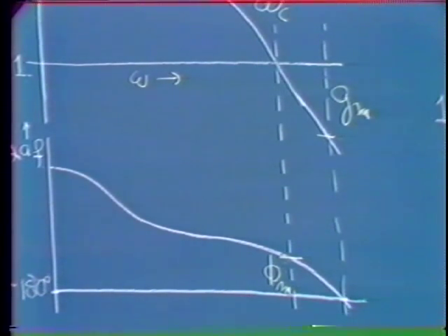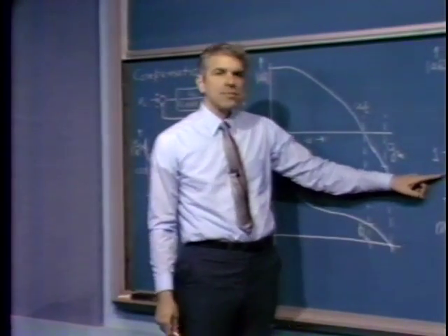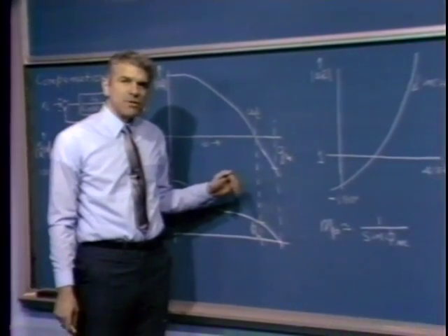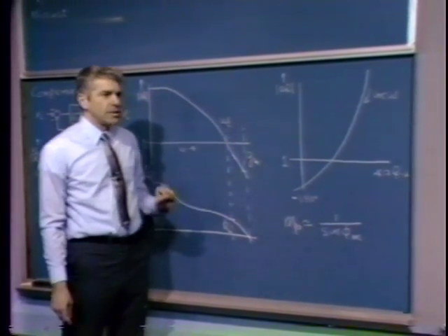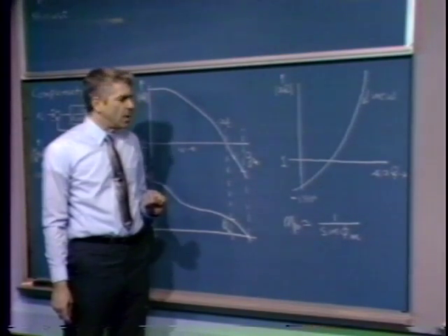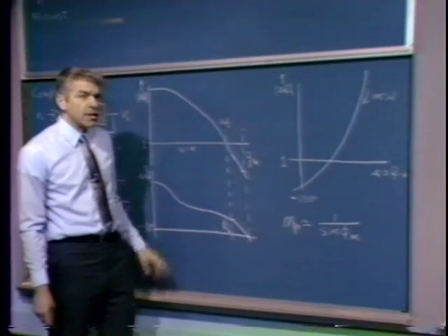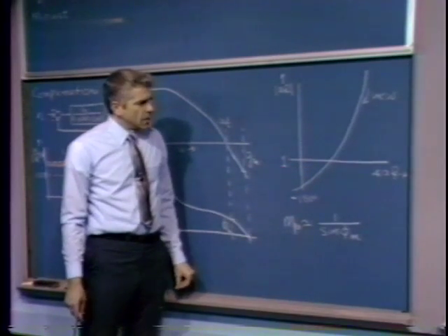We can look at those same quantities in a gain phase plot if we care to. We frequently do use gain phase plots for Nichols constructions and so forth. Incidentally, drawing a gain phase plot is a little bit more cumbersome than drawing a Bode plot, mainly because we can make asymptotic approximations, and particularly to the magnitude portion of a Bode plot, get a very, very good approximation as a series of straight line segments where we just sort of round in a little bit where two straight line segments intersect. Drawing a gain phase plot is a little bit more difficult.